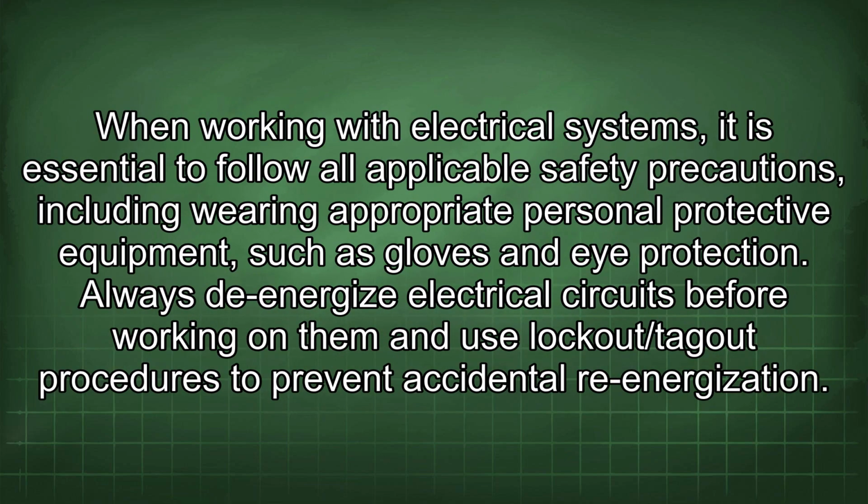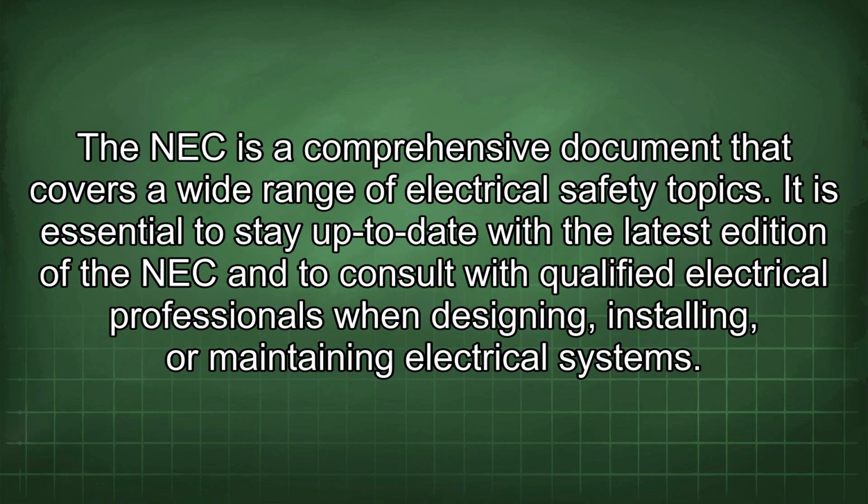When working with electrical systems, it is essential to follow all applicable safety precautions, including wearing appropriate personal protective equipment such as gloves and eye protection. Always de-energize electrical circuits before working on them and use lockout/tagout procedures to prevent accidental re-energization. The NEC is a comprehensive document that covers a wide range of electrical safety topics. It is essential to stay up to date with the latest edition of the NEC and to consult with qualified electrical professionals when designing, installing, or maintaining electrical systems.